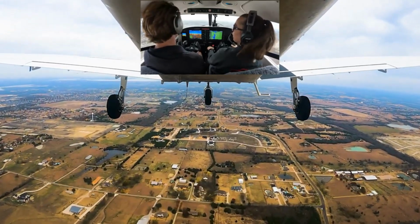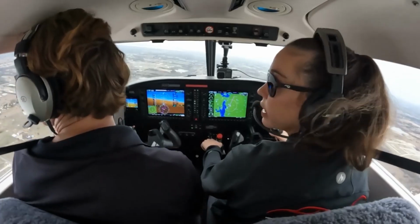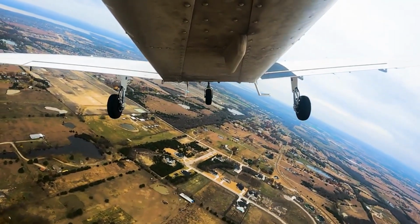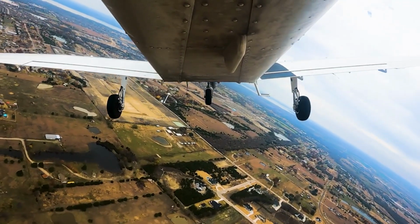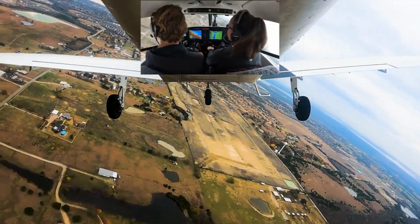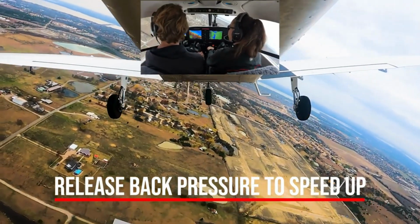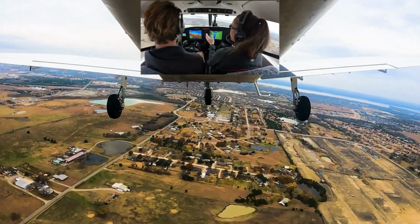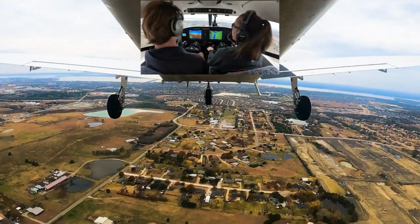Unlike a normal approach when the power setting is variable, on a power-off approach the power is fixed at the idle setting. Pitch attitude is adjusted to control the airspeed. This also changes the glide or descent angle. If an airplane is on approach with an airspeed higher than best glide, pitching down will increase the airspeed and steepen the descent angle, while pitching up will reduce the airspeed and shallow the descent angle.